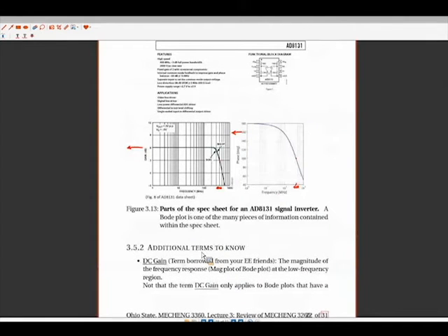And so this Bode plot gives you an idea of the operable range of this system. So at 400 megahertz, we're getting to be outside the operable range of the system. We're getting to be above a frequency where it will no longer perform that function very well, multiplying by -2. All right, and this is true of any physical system. Every physical system has limits, even really fast electrical devices. Okay.